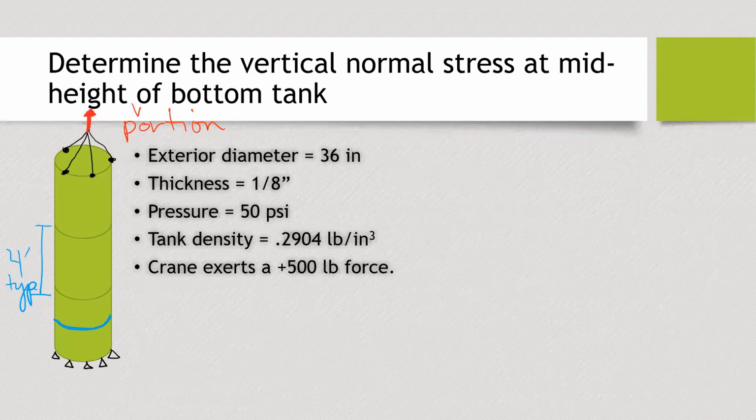So what do you want to attack first? Pressure? Okay, so we'll get the pressure vessel part out of the way. We know that we're concerned about the vertical direction. So in this case, is that my hoop stress or is that our longitudinal stress? Okay, I heard longitudinal. So that's PR over T or over 2T?